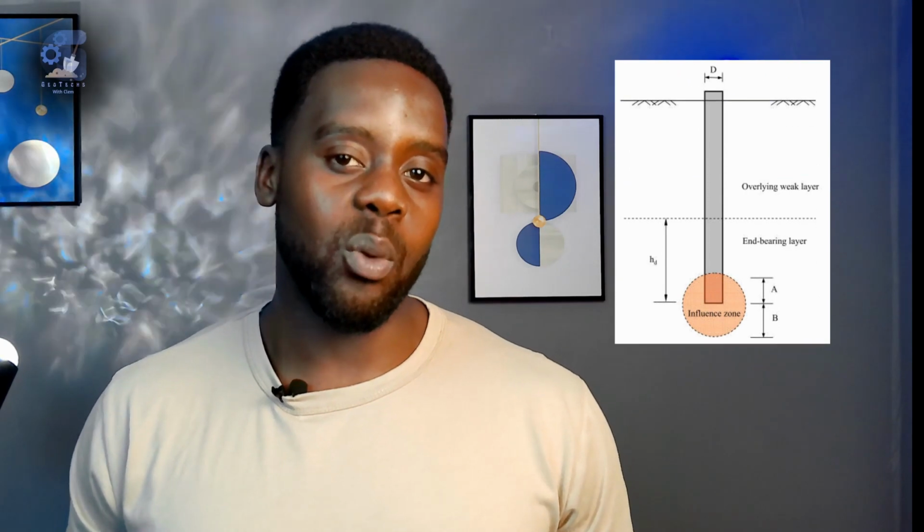Once the information from the desk studies has been gathered, the next stage is to execute ground investigations. You see, for a rational foundation design, it is very necessary to have data on the strength and the compressibility of the soil and rock at appropriate stress levels within the zone of influence of the proposed foundation. Other relevant parameters include permeability, such as for foundation works involving dewatering and grouting, and the properties of rock joints for the design of laterally loaded rock sockets.